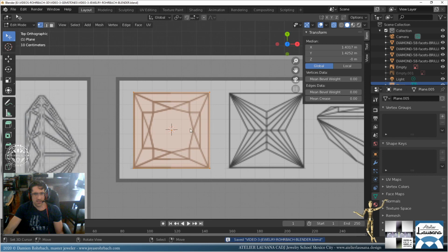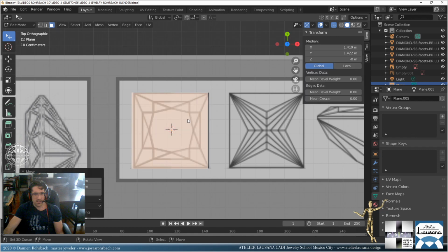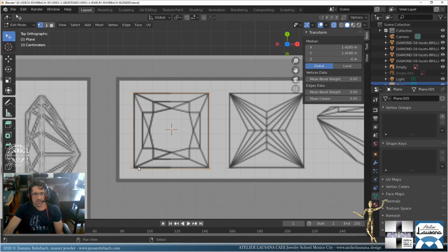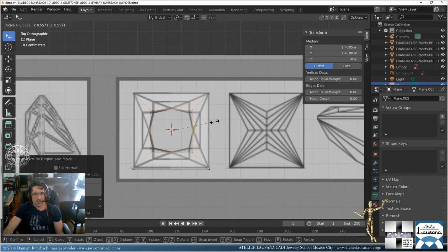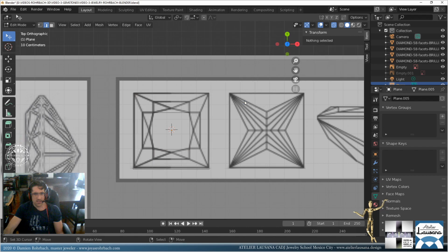Now, let's put everybody down there. The transparency is on. Now we can just remove the face without moving it, please. Okay, let's suppress only the face. We have this. We're going to take these guys, make an extrusion, click, bring it here like this, but we're going to remove these edges because they don't go there. S, only edges and faces.